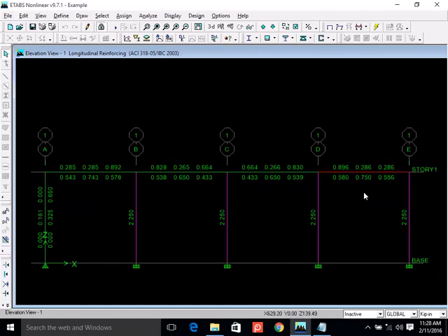I'm not going to sketch more, but you can just sketch it at the end. I just want to explain to you that at the bottom you have 3 number 4, at the support you have 3 number 4, at the support you have 3 number 4, and in the middle you can have 2 number 4, and you know where you curtail. You remember where you curtail? Exactly at L by 3. Okay?